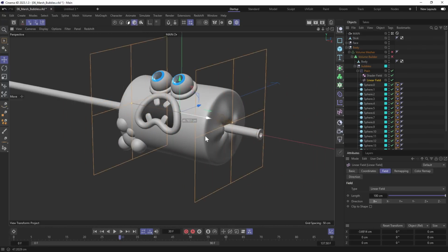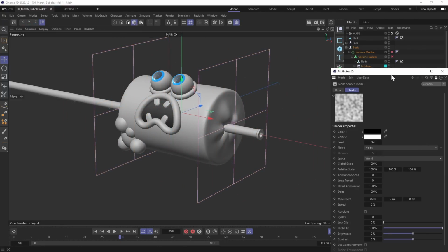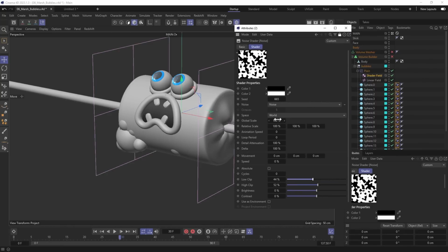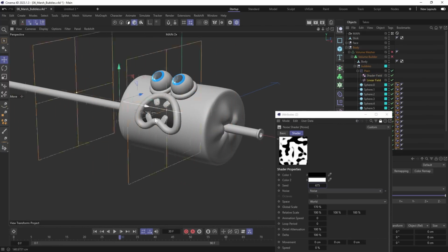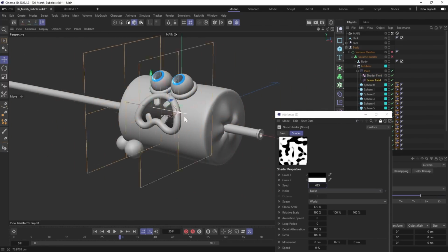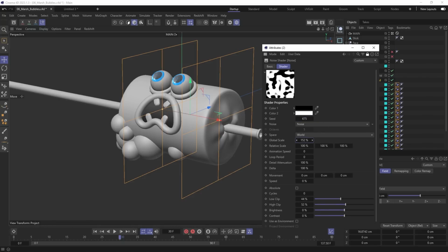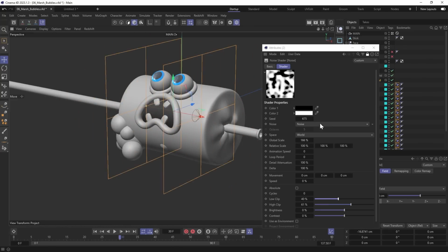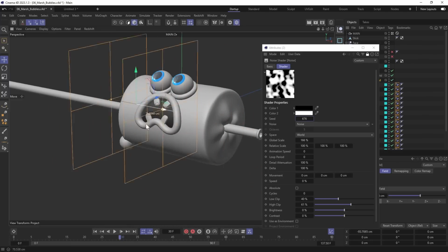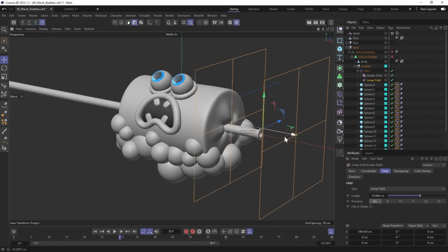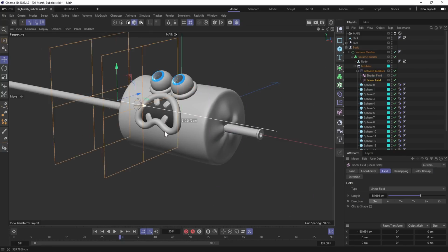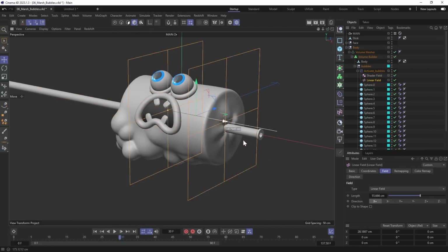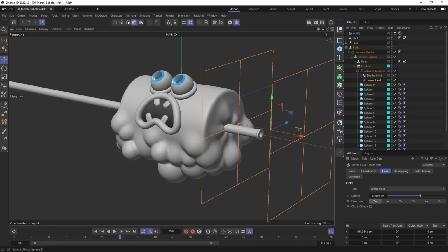Looks nice already, but I want to adjust some parameters. In particular, I want to make the noise a bit more contrast, adjust its scale, and maybe play with seed parameter. And maybe make the linear field a bit shorter. I want to rename the plane effector to activate bubbles, and in my case it looks something like this. On animation stage, we're gonna animate the X position of the linear field.